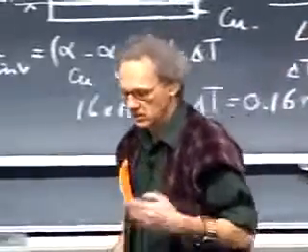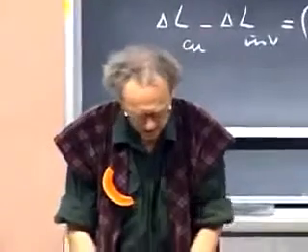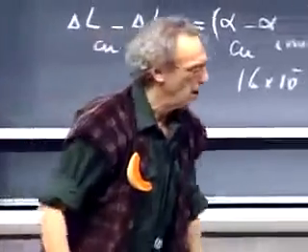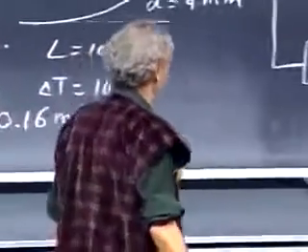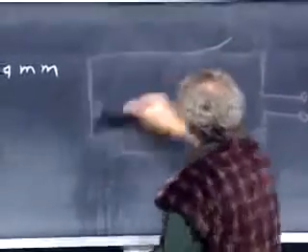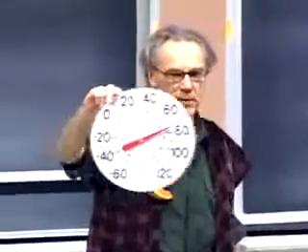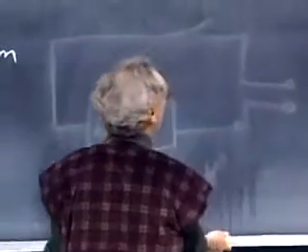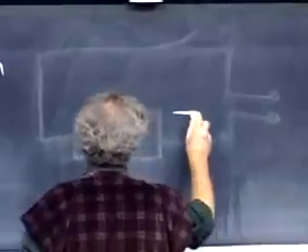So bimetals, in many ways, control matters. Thermostats, in this case, they act like a valve. Bimetals can be used as thermometers. In fact, the one that you see right here is driven exclusively by a bimetal. If you look in the back of this thermometer, and I will show that to you shortly because I broke one open for you, then it looks like this.